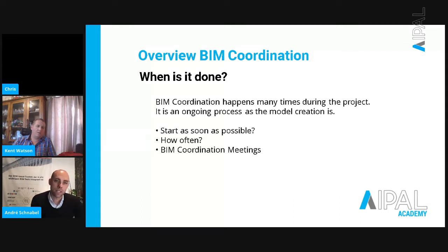I mean, I'm an architect myself. I've modeled multiple schools in the Netherlands in the BIM software, and we just sent it away a couple of years ago, to be checked. But I never had a tool to pre-check my own IFC models. So you can have a pre-work on that. So the BIM coordinator actually can work with better models in the first place. So he can focus on the multidisciplinary aspects, and can use the more complex checks.